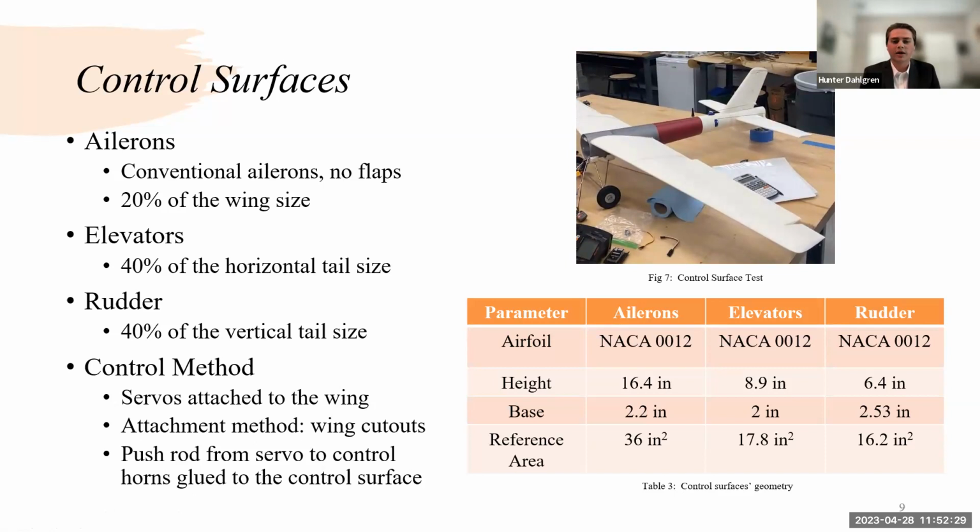Then on each control surface, we had a 3D printed control horn that was super glued onto it with a push rod attached to the servo and the control horn. Next slide.